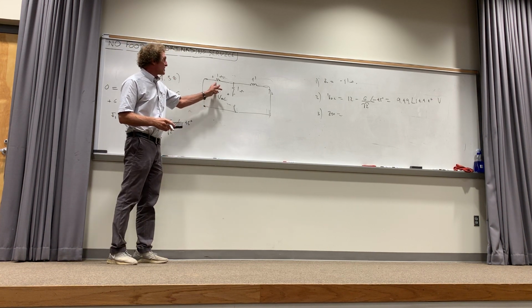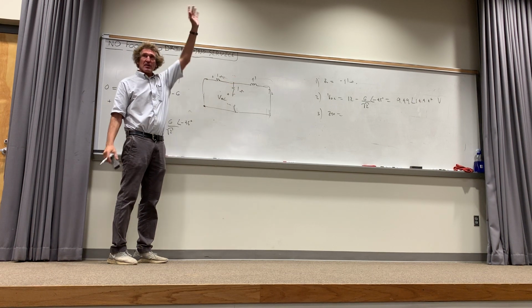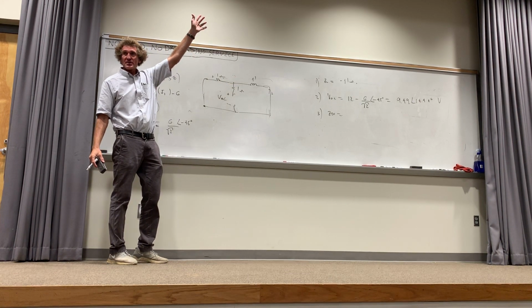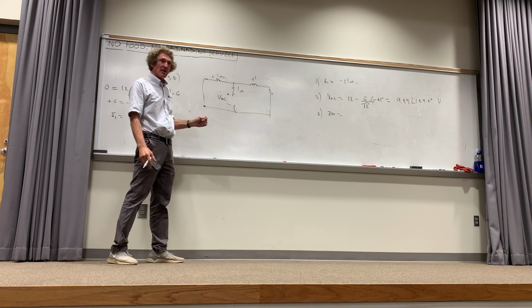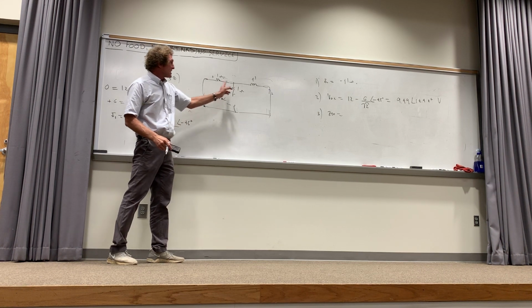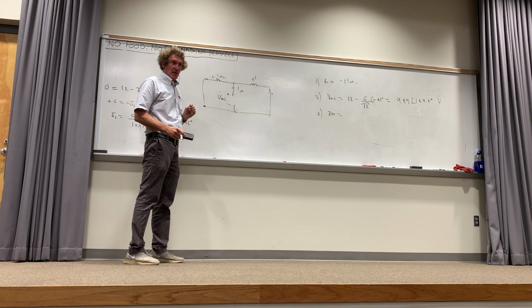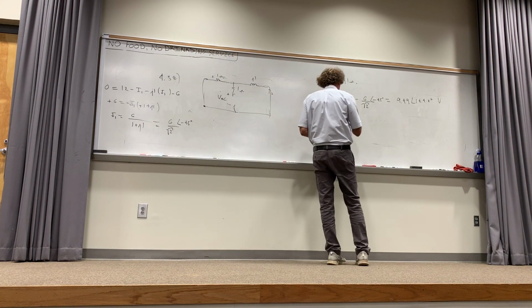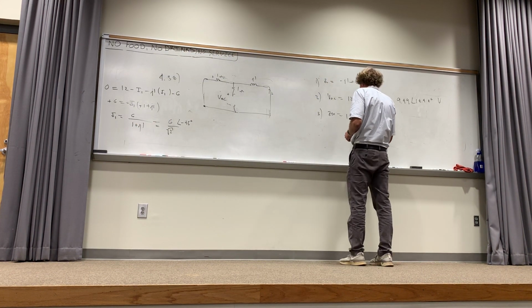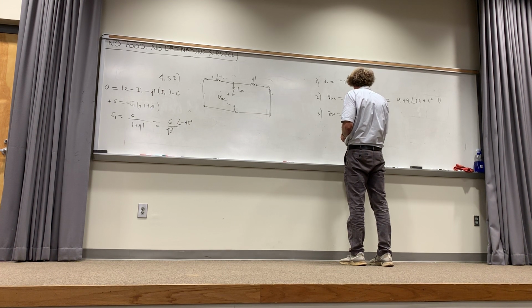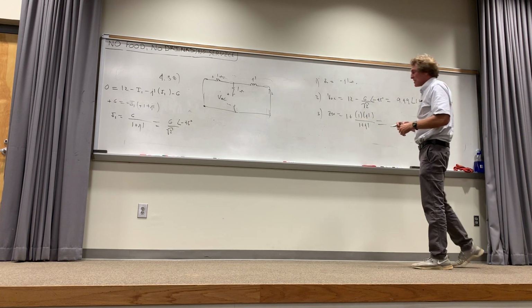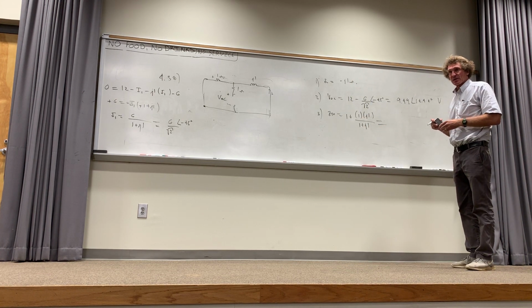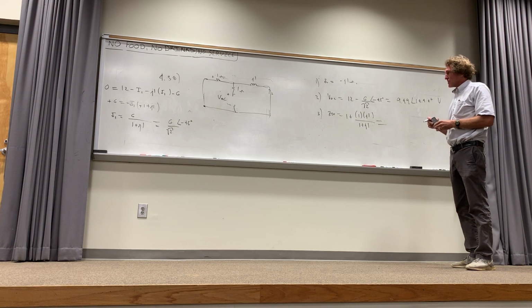How many see this 1 and that j1 are in parallel? Show of hands. Y'all see that? They are in parallel, right? It's important. This is in parallel with that now, right? So it's going to be 1 plus that. So it's 1 plus, and the parallel combination would be just 1 times j1 over 1 plus j1. Now that's going to have a magnitude and an angle as well, isn't it, class? Give that to me if you don't mind.